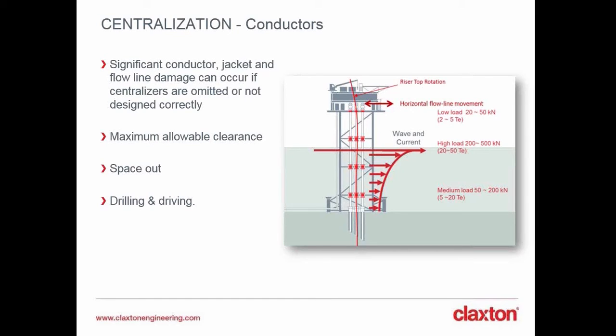So lateral support for the conductors is required just to withstand the loads, and in the little diagram on the screen you'll notice that there are some loads shown in the sketch. You have wave and current loads identified there. There's a typical profile of wave and current loads that's typical for the North Sea.